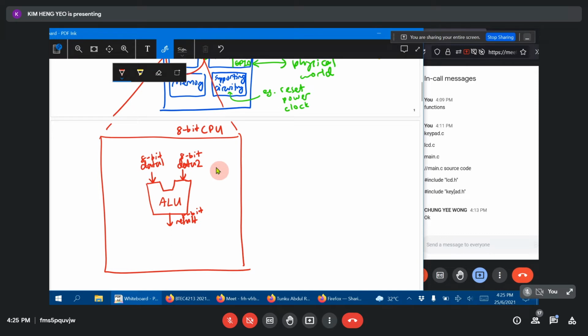When the processor consumes a lot of energy, it's going to heat up. When the processor heats up, then you're going to need to cool it down using a heatsink or other forms of cooling systems. This will increase the size and cost and power consumption of the whole device. So it's not practical for that. And that type of processing power is also not required. So microcontrollers are generally 8 bits or 32 bits.